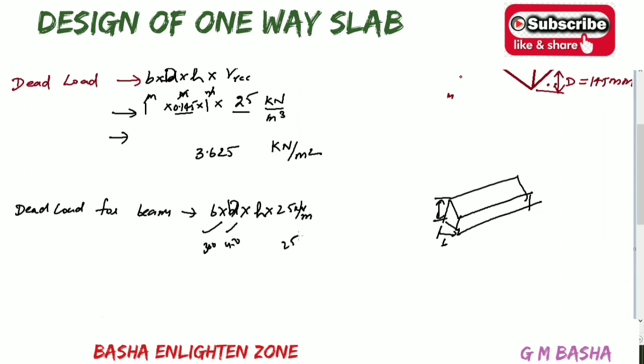Here it will be 25, and we can take this H value as some 1 meter. If you cancel this you will get the entire value in terms of kilonewton only. Here meter cube means meter, meter and meter, but the overall value we get here is kilonewton, but we are considering only for 1 meter because this is a beam.